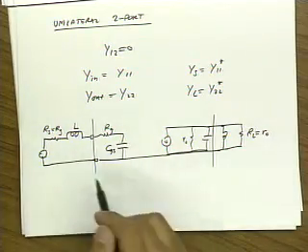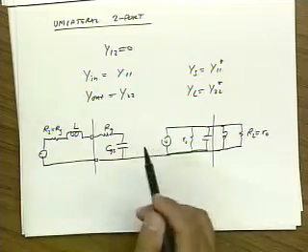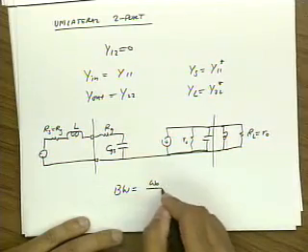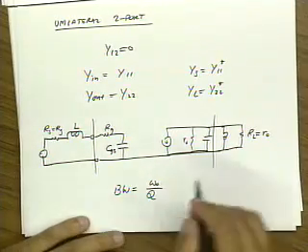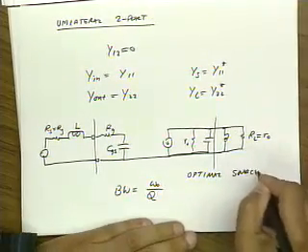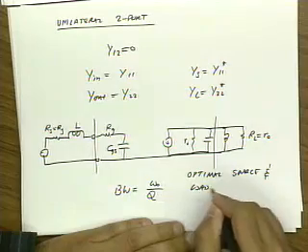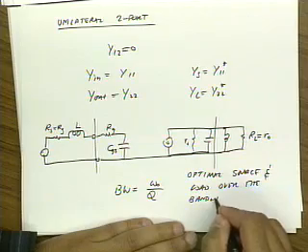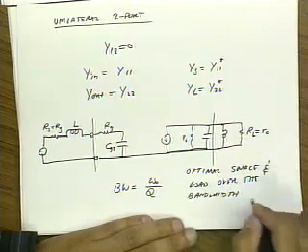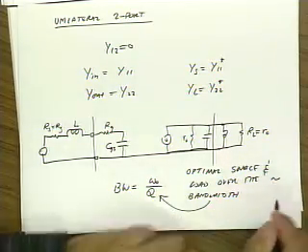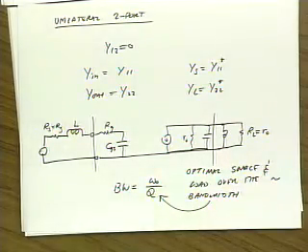And so what I'll find is that this optimality condition holds over a bandwidth which is determined by the quality factor of my circuit. So I have optimal source and load over the bandwidth. So when I say over, I mean approximately over this bandwidth. I have a good input and output match, and therefore I have maximum power gain. All right?